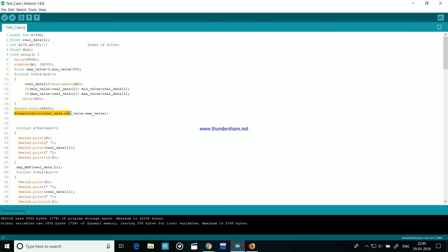This is my normalization function. In this function I have taken the data collected from the pulse to mean 0 and divided by the maximum value to get the data from -1 to 1, so that all the samples lie between -1 and 1. This makes it easy to find and process the data further.